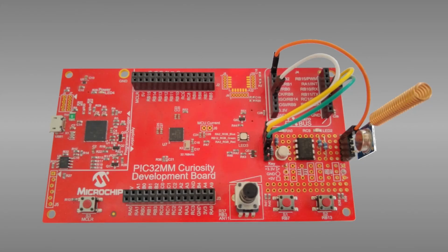Let me put out a few technical details about this key fob. The complete software in this key fob has a size of about 23 kilobytes. Not just MTE, everything. The whole application. It uses a bit less than 4 kilobytes of RAM. The processor is a MIPS 32 core running at 8 MHz, but at the current data rate of 2000 bits per second of the 433 MHz transmitter, it takes about 100 milliseconds to transmit a command over the air, and it takes MTE not much more to encode the data. In less than half a second after the beginning of a button press, the receiver knows what to do.